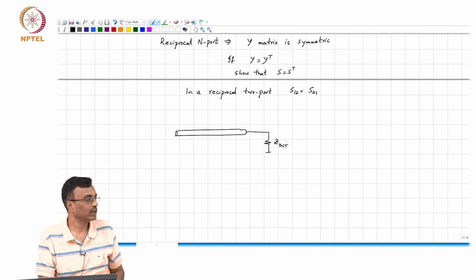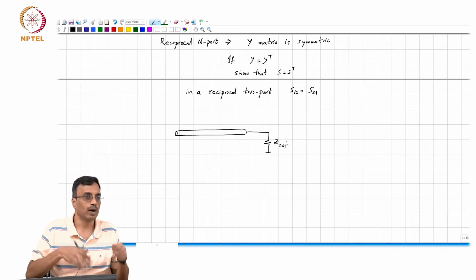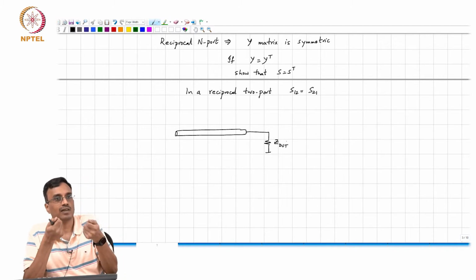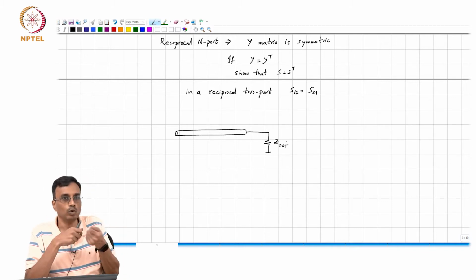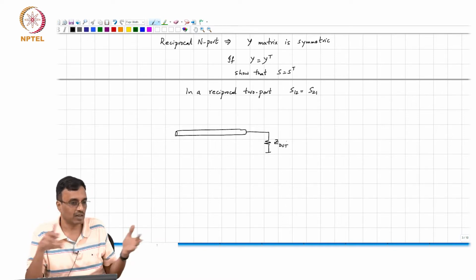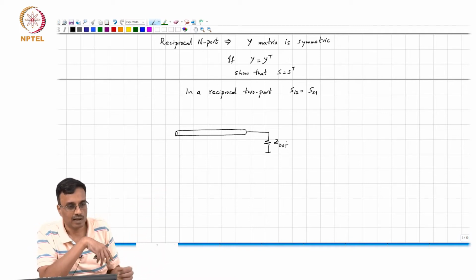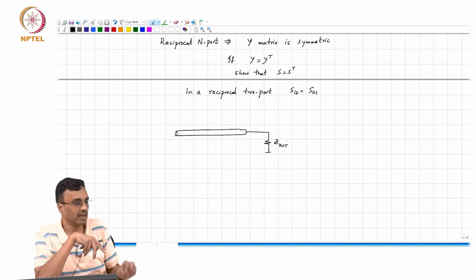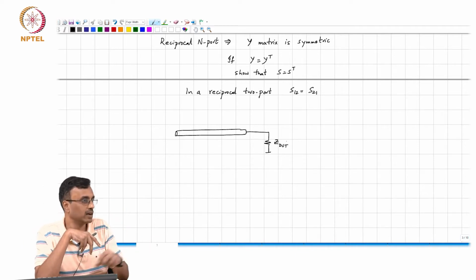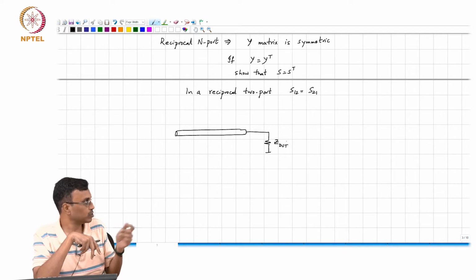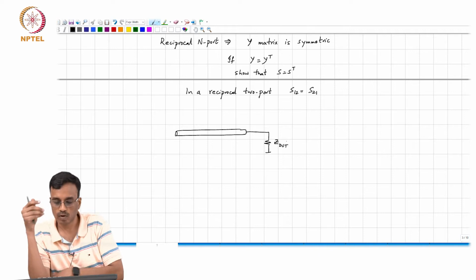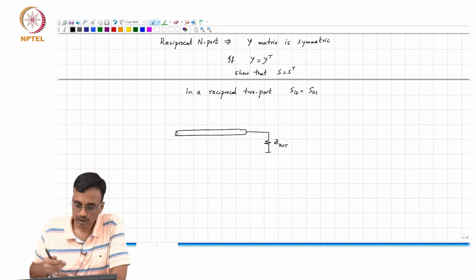Even with a one port, even though there's potentially no issue with stability, you can't put the voltmeter and ammeter right at the two terminals of the impedance you want to measure. The measurement equipment is some kind of box, and Z DUT is some tiny thing somewhere, and you need some kind of cable or interface to go from the box to the DUT, and therefore you have a transmission line.